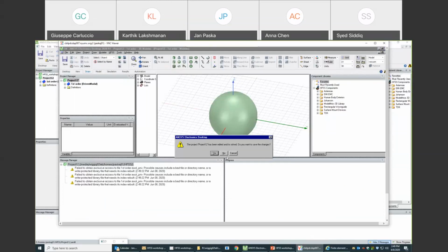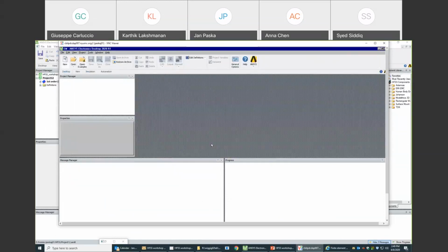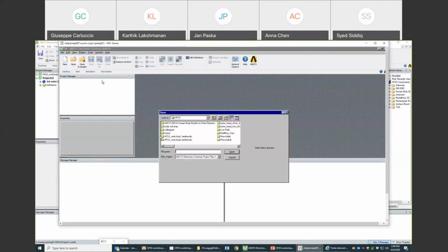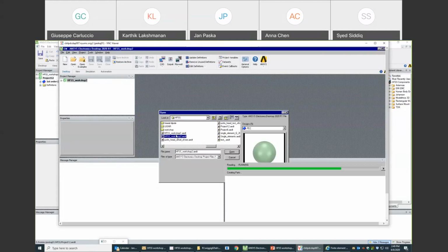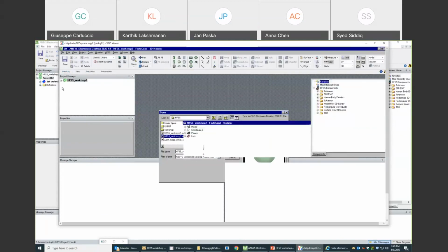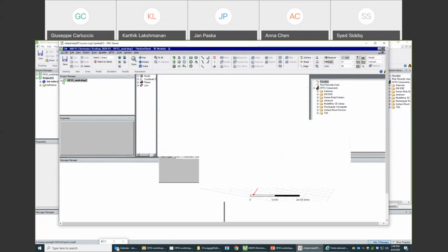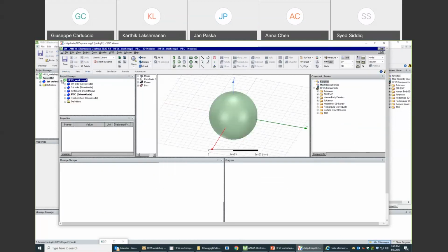No, because I gave it a material of copper. Okay, so you define the conductivity. When I was doing it, I didn't thicken the sheet, but I gave finite conductivity as a boundary condition. But then in the finite conductivity, you can also choose the material. Then I chose it as copper.